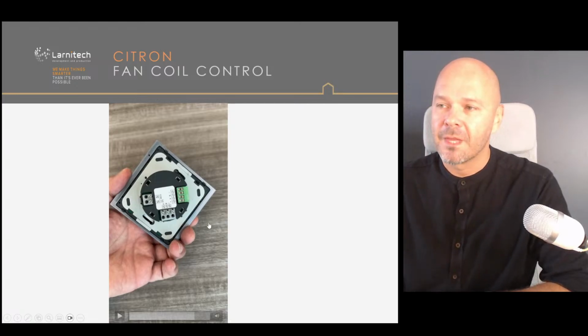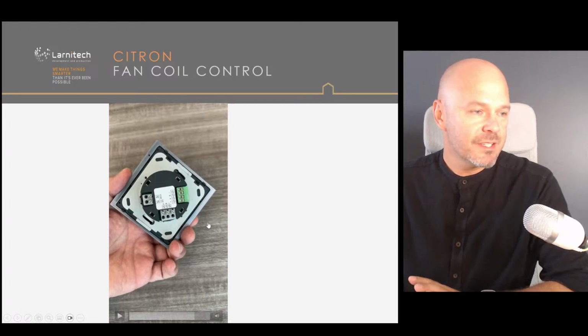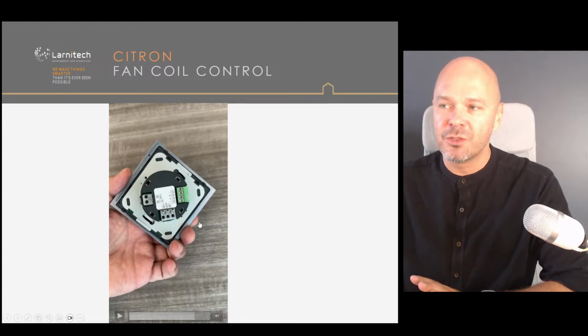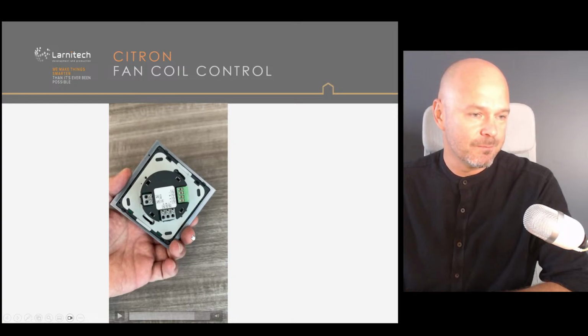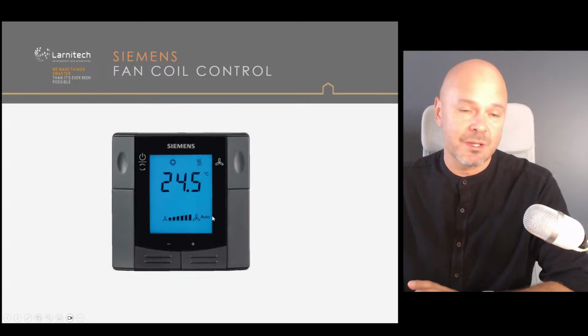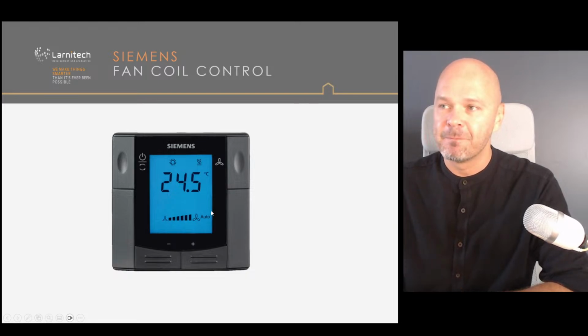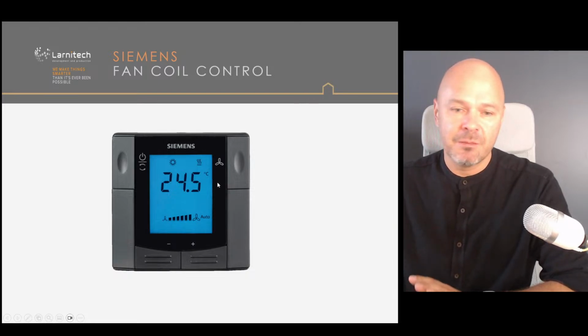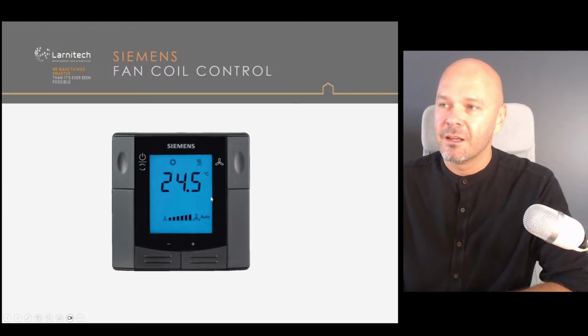Okay, so is this okay for you? Is this understandable? So this is what you do when you connect to a fan coil. The next part is, oh yes, we can also use Siemens, we can also use some other brands of thermostats. Siemens is maybe one of the most popular for many installations. So the Siemens with Modbus inside we can also use.